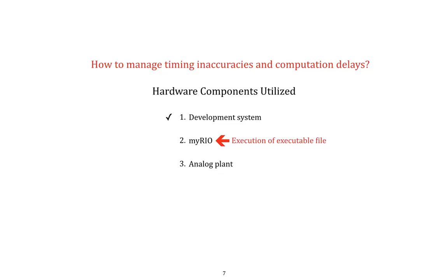And just a bit of terminology here, when a process that relies upon precise timing of its events is executed under a real-time operating system such that sufficiently precise timing of those events is achieved, the process is said to have been executed in hard real time. And that essentially is how we'll use the MyRIO, that is to execute in hard real time our discrete time control laws, hardware in the loop with an analog plant.